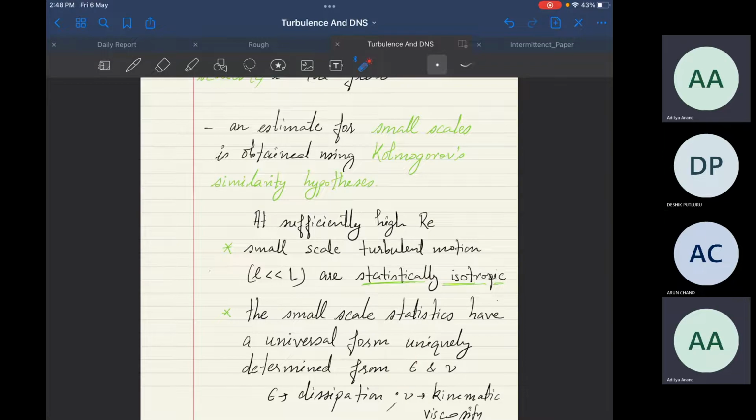So what is this dissipation rate? We all know the kinematic viscosity, but what is this dissipation rate? In turbulent flows, the velocities are fluctuating randomly and violently. From the fluctuating part, you can calculate the RMS of this fluctuating part, or you can say that these random intense fluctuations have some energy to them. So this is called the turbulent kinetic energy of the flow.